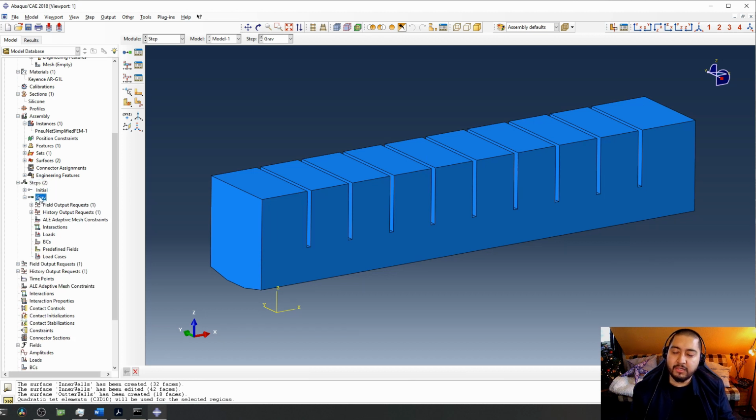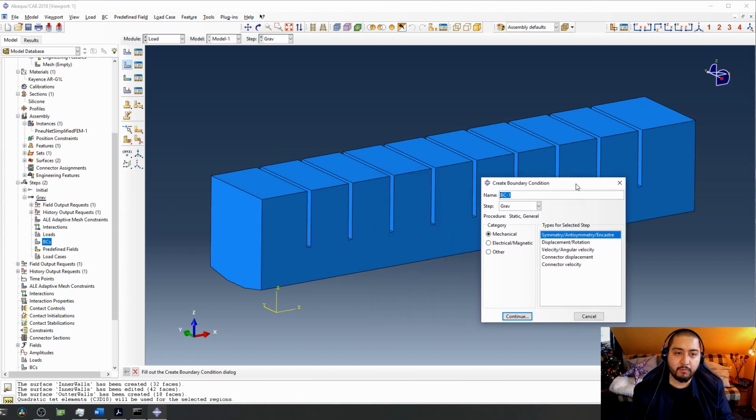So we have the first step, and in the first step we already have two boundary conditions that we need to address. To add boundary conditions, you double click, or as always, right click on create boundary conditions, and then we have this window pop up. Here I will create one named fix end in order to fix or support, otherwise it's just in the air.